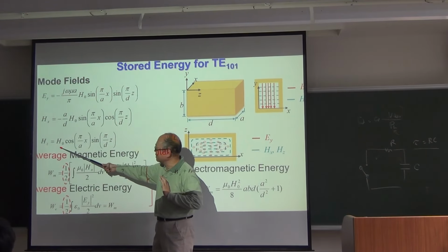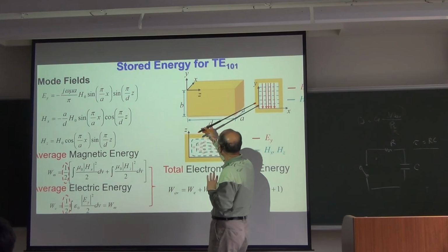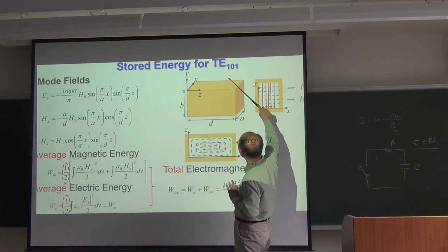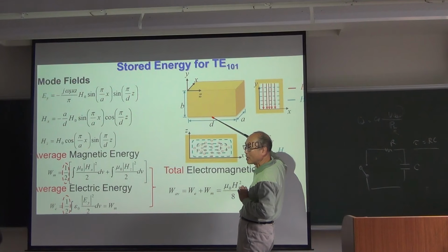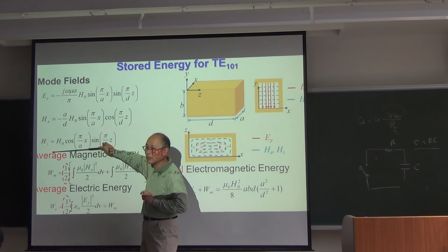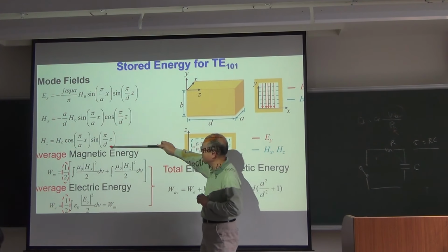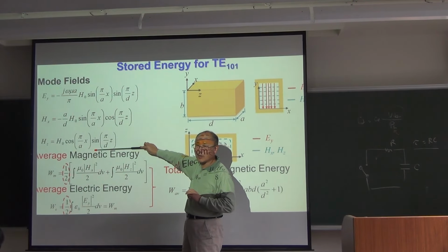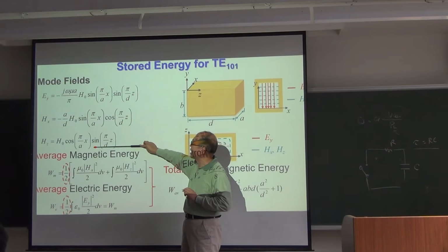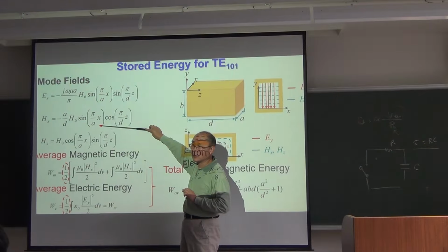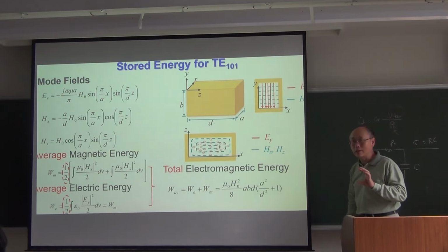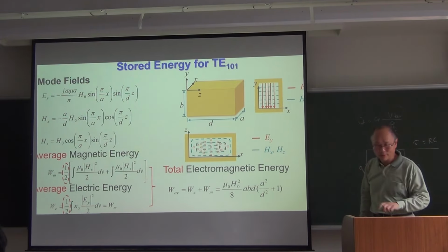And for this, the z component of the magnetic field is along this direction. So you have this surface, and the surface in the back, and the surface in the bottom, that has the surface current associated with this term. So you have 4 surfaces that you have to calculate the ohmic loss associated with this term. Another 4 surfaces associated with this term for the surface current. So totally, you need to calculate 8 surfaces for the surface current.